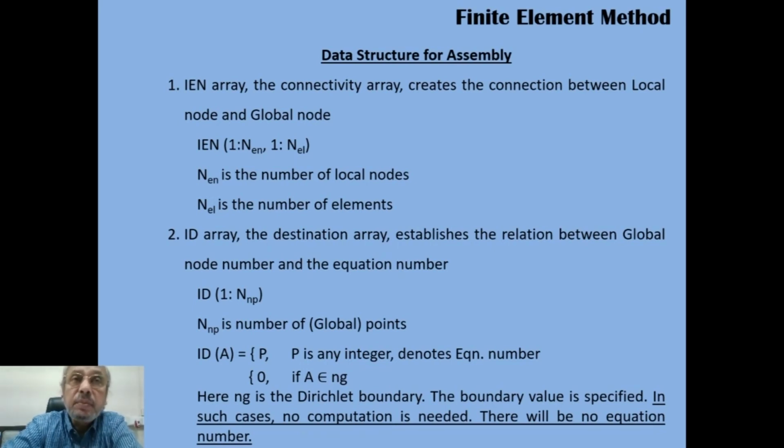And finite element is again an integral method to minimize the error, and this is also a subdomain method, but this weighting function has to be determined, and when we use Galerkin weighted residual method, this weighting function is exactly equal to shape function.